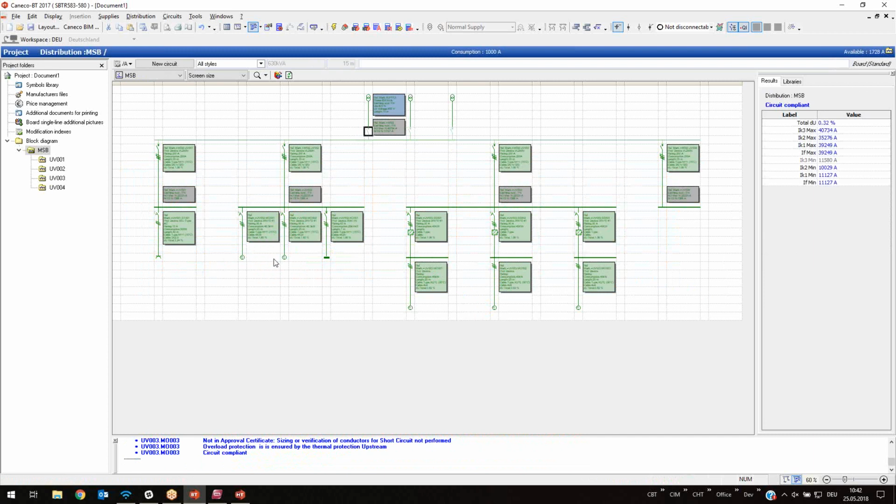Okay. But back to the main bus bar where the drives are connected. In case some of the motors are contributing, this means that this bus bar will not be sized as the sum of all the three drives. Is there any place to indicate that the load in this bus bar is less in reality? I am not sure whether I explain myself properly.